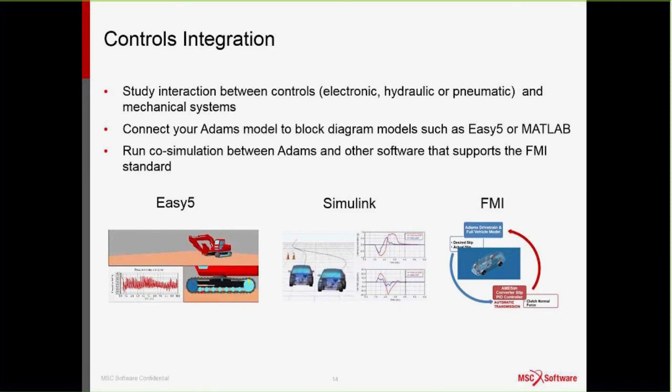So in order to connect your Adams model to a 1D diagram model like EZ5, Matlab, or any control software that supports the FMI standard, you can use Adams controls to link those two disciplines together and study the interaction between the controls, electronics, hydraulics, and your mechanical systems like a full vehicle. And the product here we use is called the Adams control, which we will illustrate later in the demonstration.